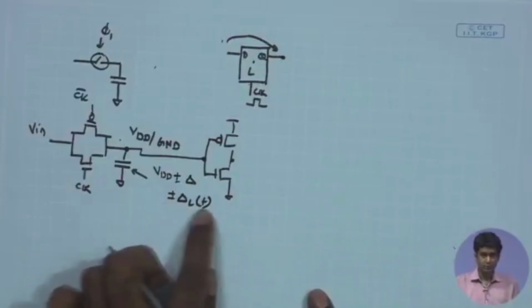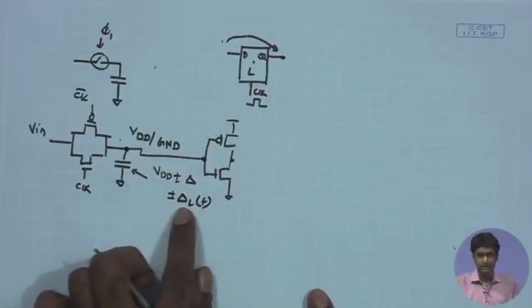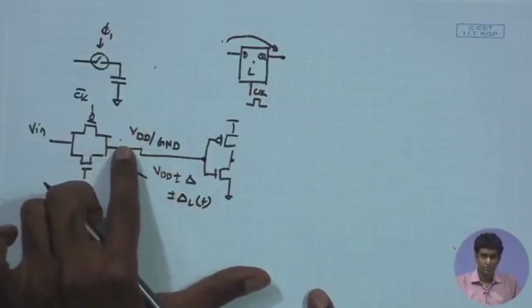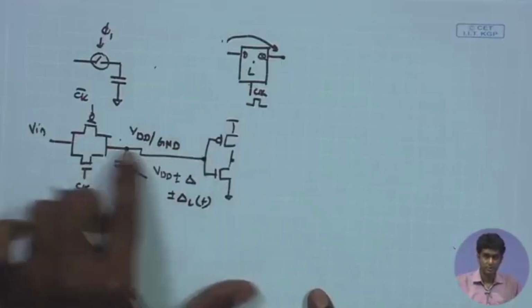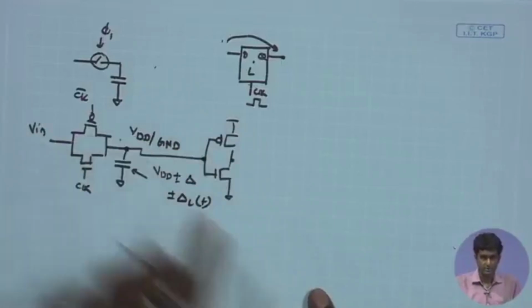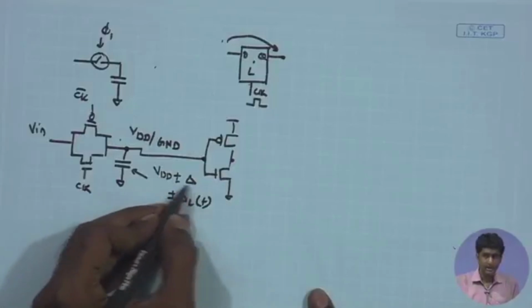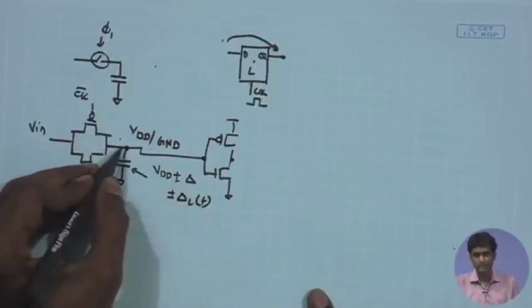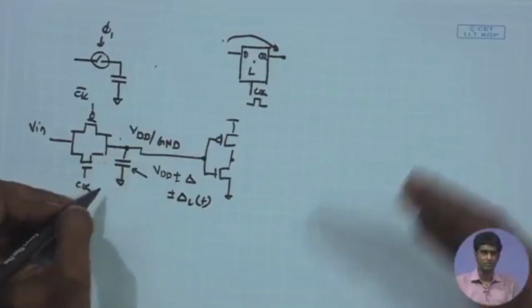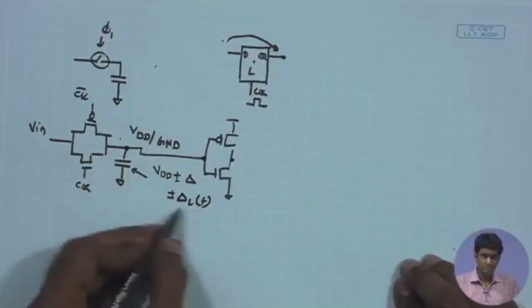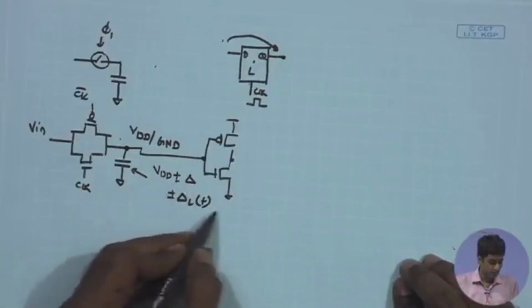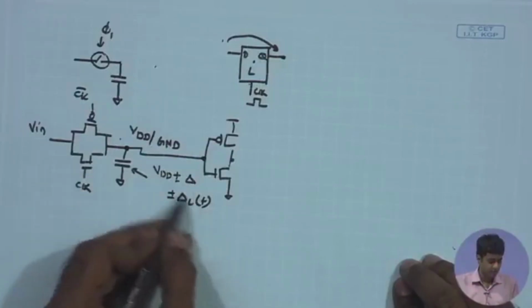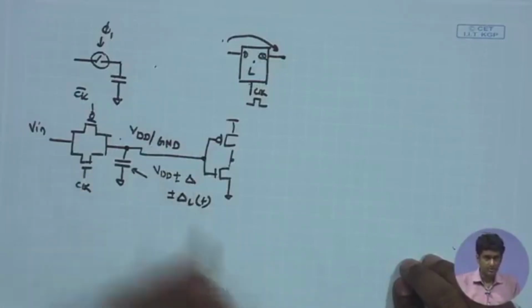leakage component which is also going to be delta leakage, a function of t. So, this voltage component may be time dependent, it will change this stored charge in a time dependent fashion depending upon the leakage constituent of the different MOSFETs to which this voltage is connected. So, this delta is coming at t equal to 0, while sampling itself you have some error coming, as we have seen, because of clock feed through, charge injection, etc., and then you have a time dependent component which can be because of leakage. As a result we may have overall change in the voltage over here as a function of time. How much change can be tolerated?